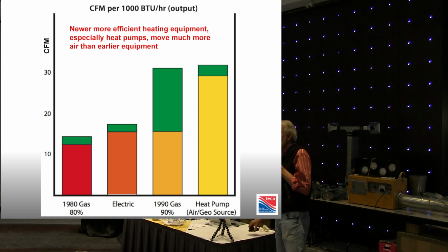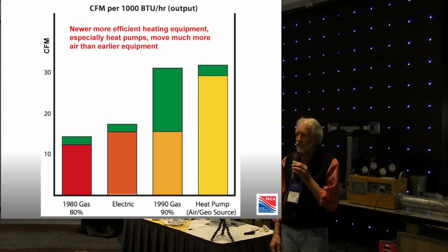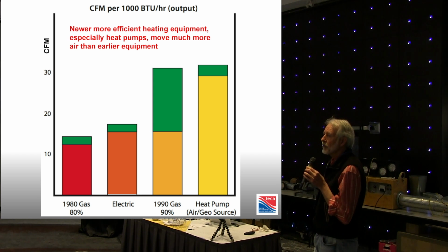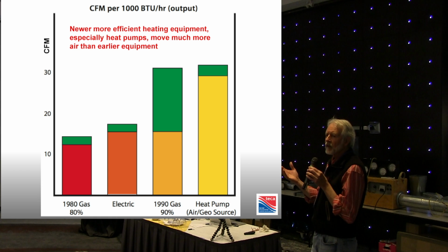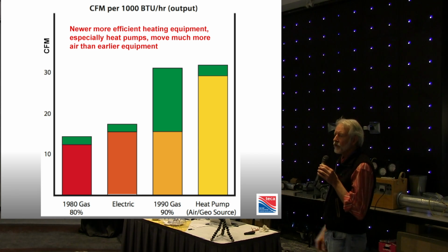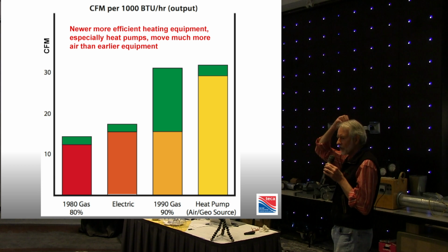So anyone today who takes out an air coil and puts in a heat pump and matches the BTUs is an idiot, because you'll destroy the compressor. And people might contest these kind of outrageous statements, but you can't fudge physics. I dropped one on the provincial government right now because they're trying to launch a heat pump program, and I think they've got rocks in their head.